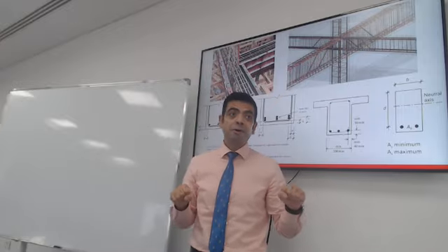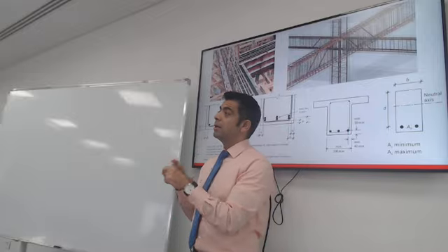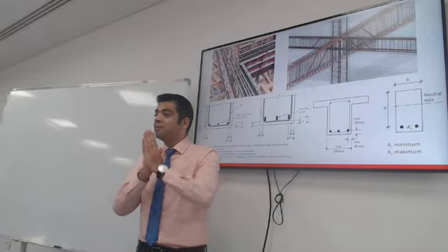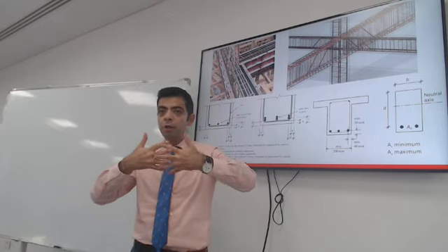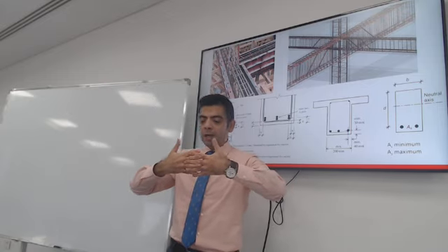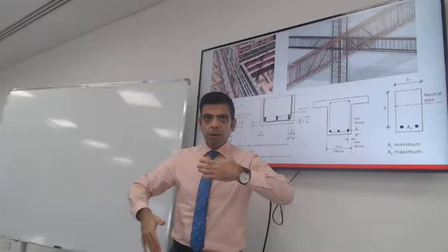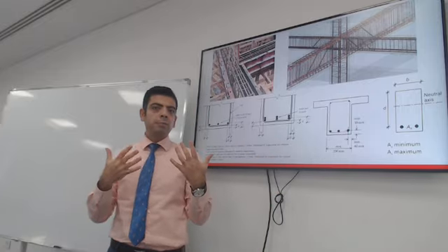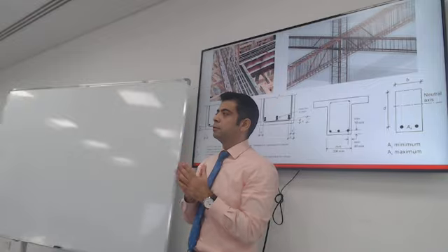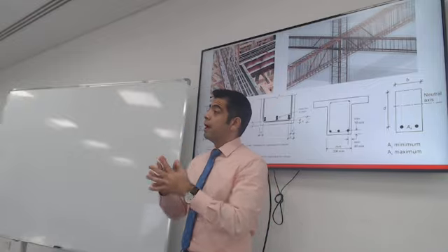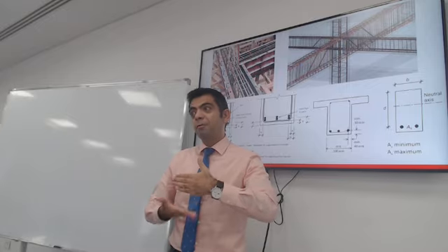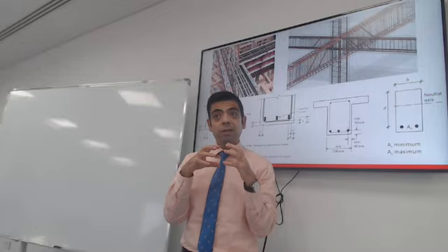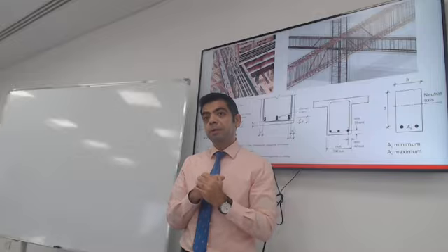Steel is very strong in tension. Concrete is terrible in tension. Concrete almost has no strength in tension. As a matter of fact, if you put a load on an unreinforced concrete, it will just crack into two, it will split into 2 halves at not a very big stress compared to steel. So whenever you have tensile stresses, you want to have reinforcement there. What concrete is good for is compression. It can take quite a bit of compression.